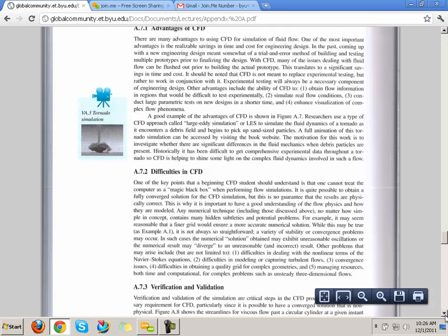So one thing that is done in industry is they want to calibrate their CFD to make sure it is reflecting accurate results. They may run a CFD analysis of something simple at a low speed, and then go to a wind tunnel with that object as well and do a real test on it and make sure the two match.